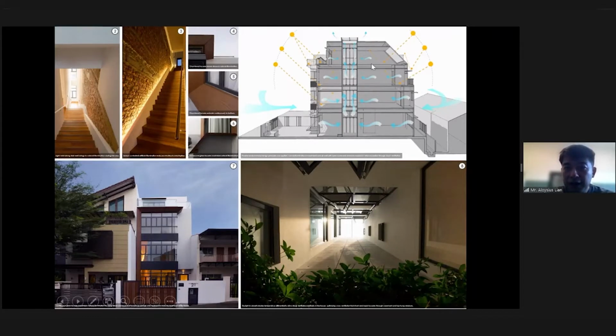we have this central courtyard in which we make the central courtyard hotter than the rest of the house. So this would create a kind of stack effect where the air is drawn in through here. The windows that you see here are closed, but when the house is occupied, most of the time the elderly couple will keep all their windows open. And this actually draws in the air upwards through this courtyard that you see here.